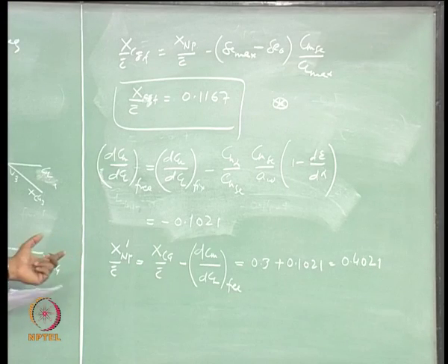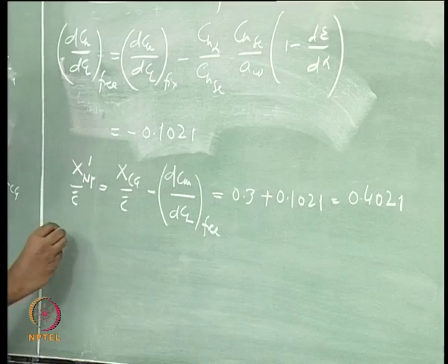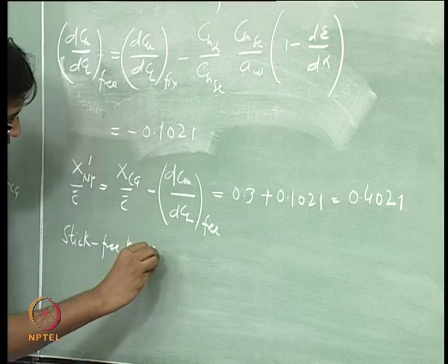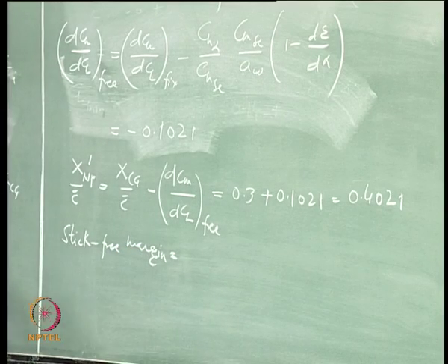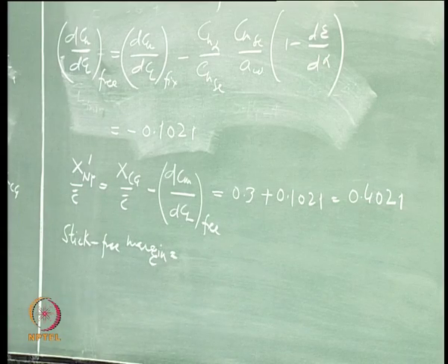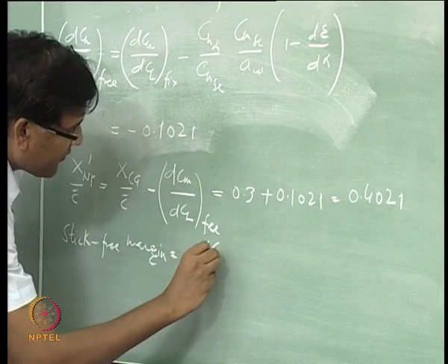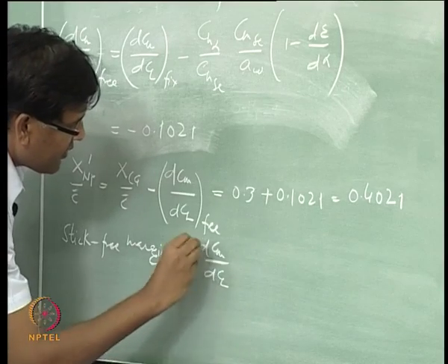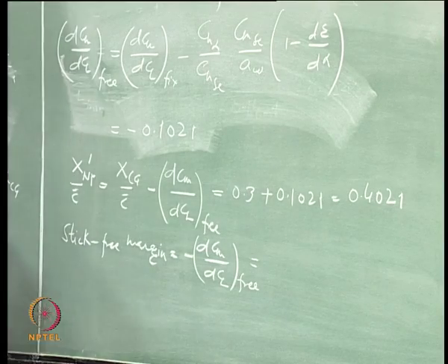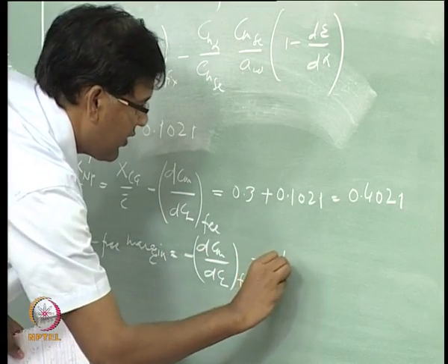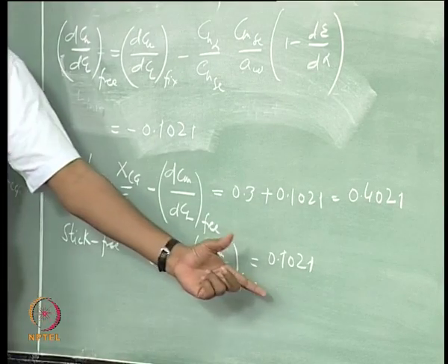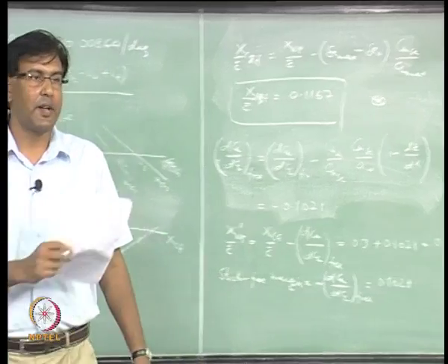And the stick free margin is this minus this, which is 10% of the mean aerodynamic chord.